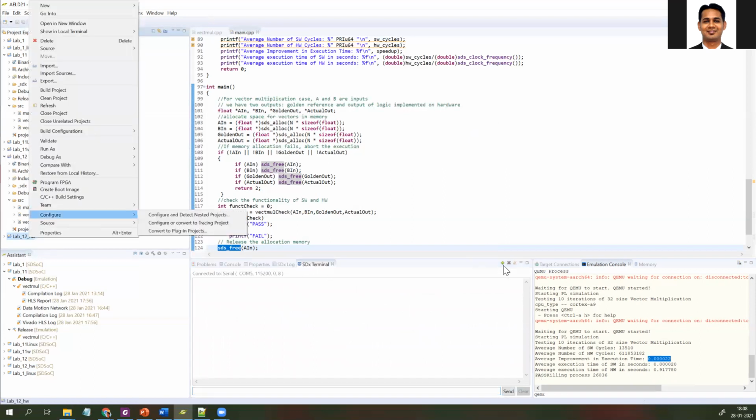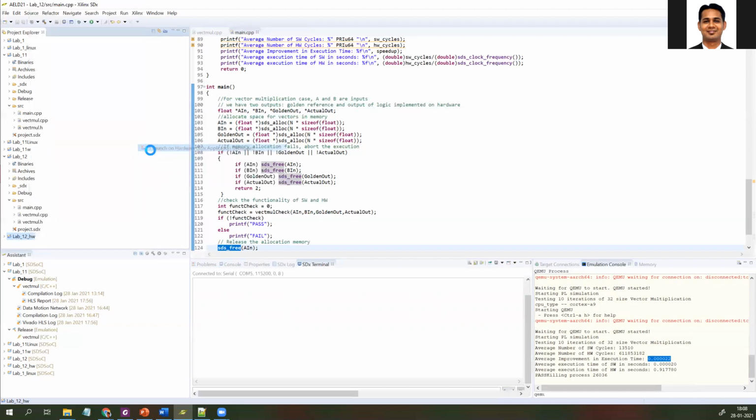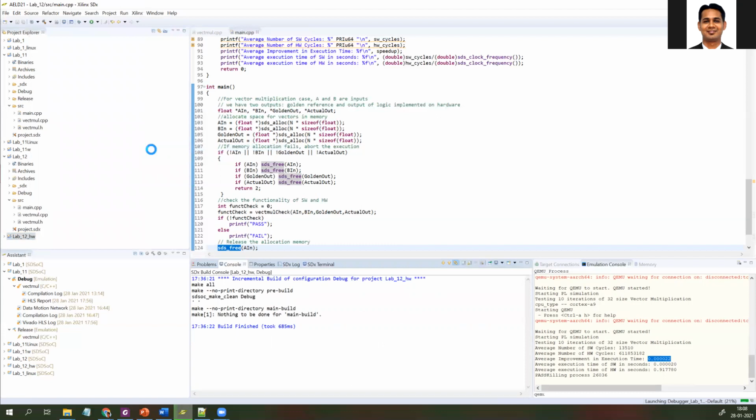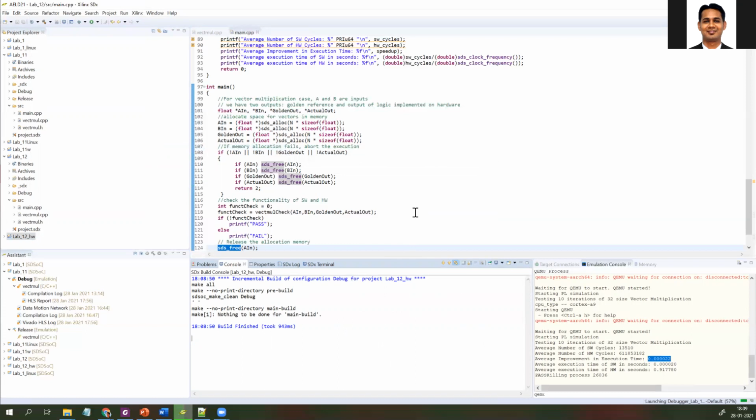If you want to connect it, you just need to click on plus and then select the appropriate terminal, in case you have access to the board. But if you don't have access to the board, you can use the other method of Linux-based implementation. In this case, first the FPGA will get programmed, and after that, your ARM processor will get programmed.